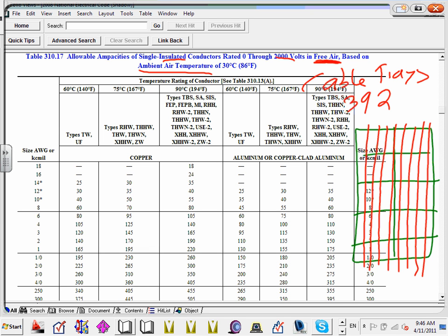Where would you use a cable tray? If you decided to use 2000 kcmil conductor and you don't want to pull that baby in an EMT conduit, a cable tray would be perfect for this type of conductor. A 2000, a 1000, a 900, a 700 kcmil, but in a cable tray, perfect. Because cable trays, guys, are open, so you just lay them and tie them and off you go. Okay, so if you were to use a cable tray in this application, if you don't believe me, go to Article 392. It will tell you that you use this table to find it.